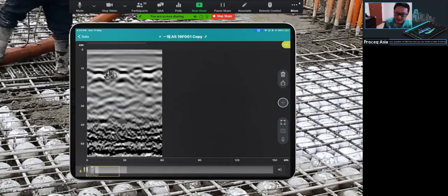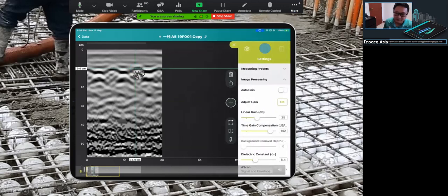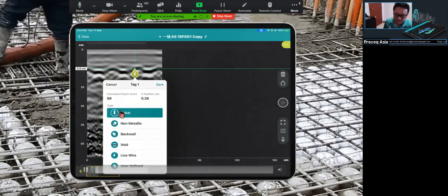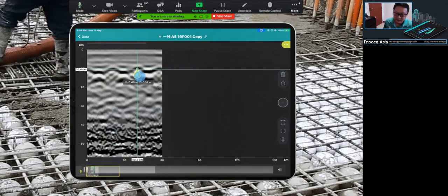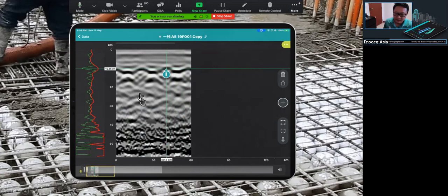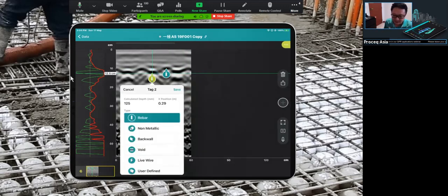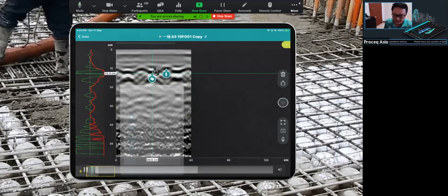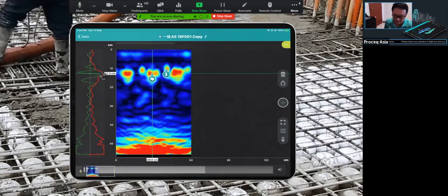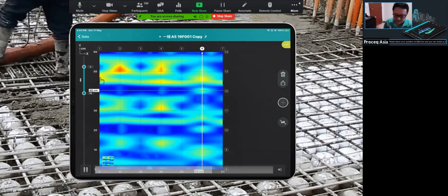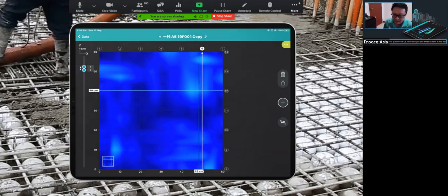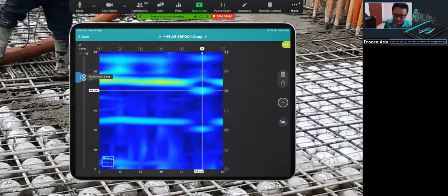So basically over here, I can see a clear reflection from the metallic rebar mesh. And below here, there are three hollow PE balls, just beside the rebar, in between the spacing, giving you black and white. We use the total signal reflection, which we call the envelope.